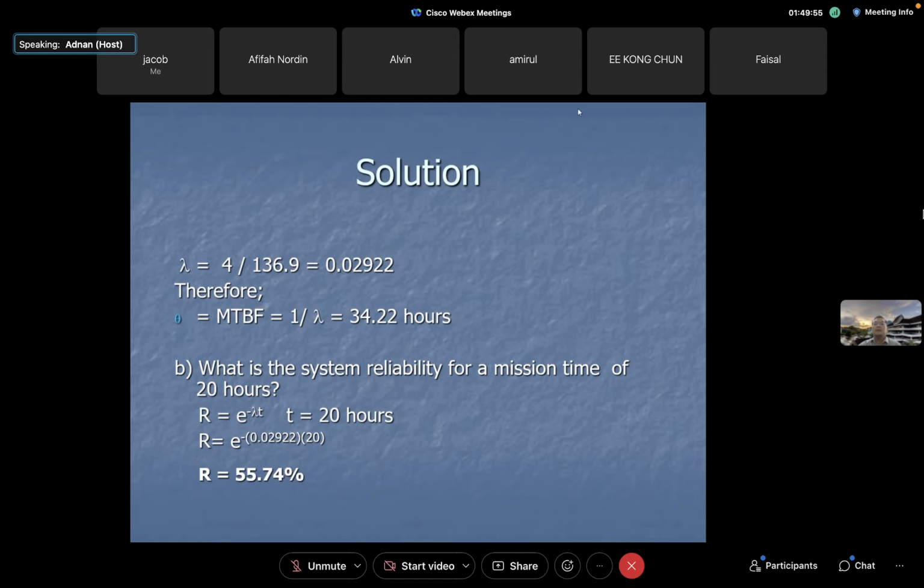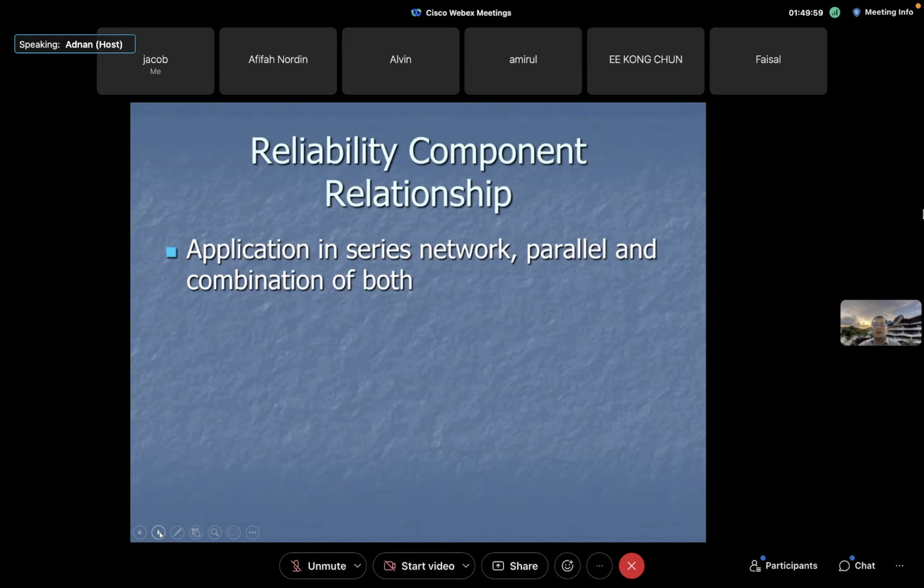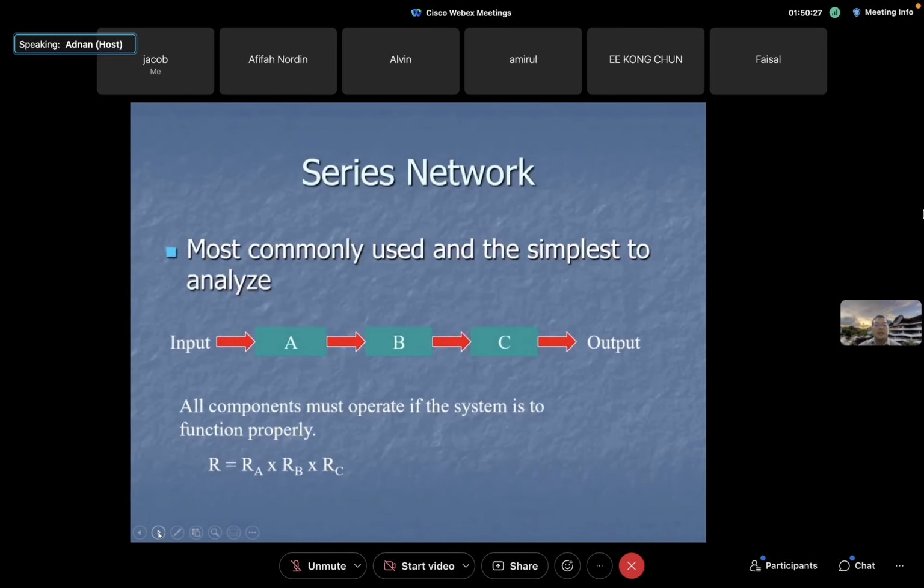So what I'm explaining here is some basics of reliability. At least you have heard of reliability. How do we improve reliability in the design stage? As a design engineer, you want to know how can I improve the reliability of products? You can use what we call serial design or parallel design, where you can have a backup. Some equipment have a backup component. One component fails, the other one will take over. So this is when we improve in design.